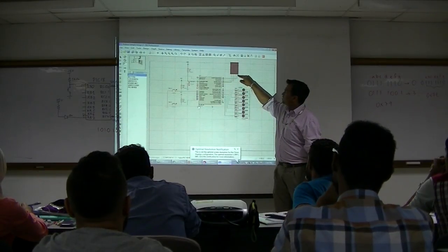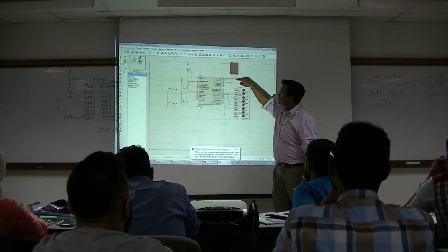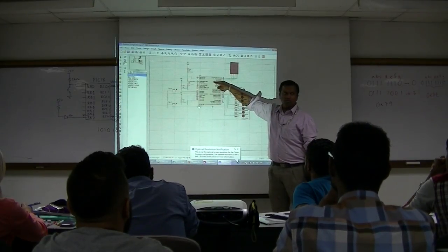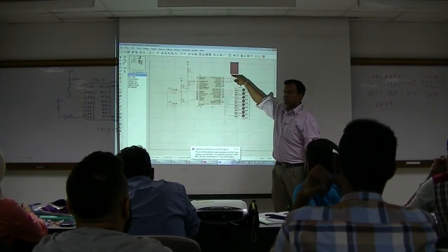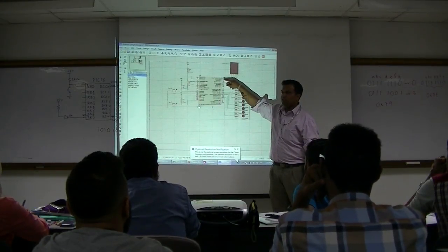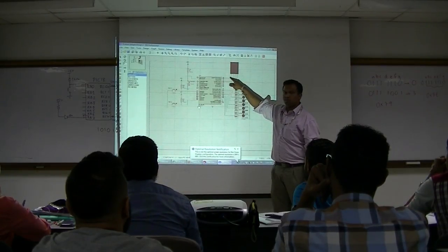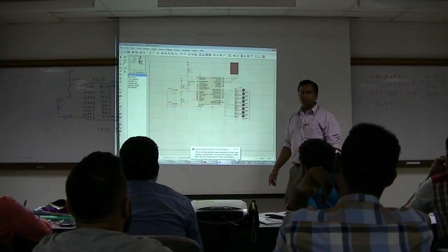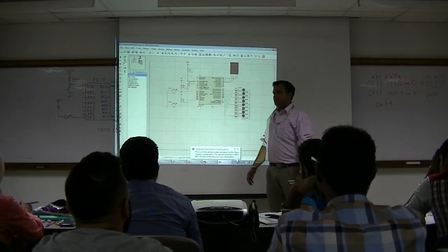So you must make sure that the pins are connected correctly. So this is actually 0, so you connect to port C pin number 0, whichever port. So this is 0, 1, 2, 3. So this one should connect accordingly to pin number 0, this should connect to pin number 1, this should connect to pin number 2, should be connected to pin number 3. Then whatever value that you display, you can display it here. Is it okay?